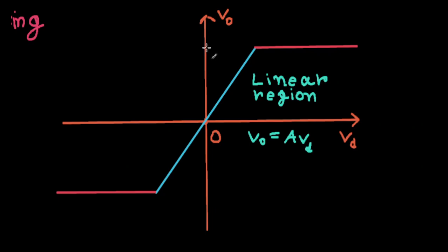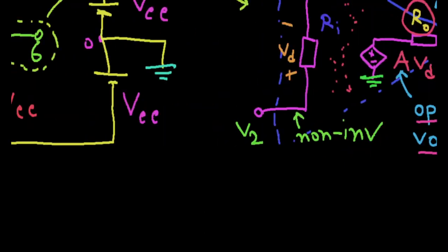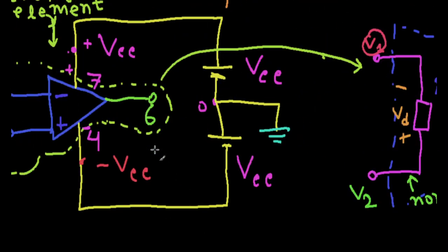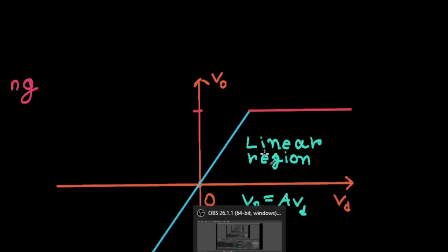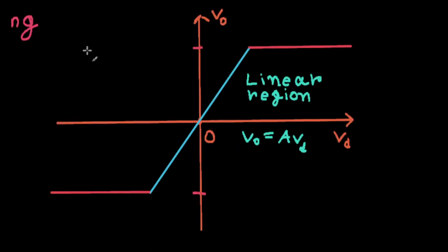Very interestingly, this is one other place, and might even be the last time or close to the last time, we're going to mention the power supply for the rest of the series. But anyways, the maximum and minimum output voltages here are actually limited or determined by your power supply. If you remember this, we'll just look back on it, the positive power supply and negative power supply. So this was plus VCC, this was minus VCC. In other words, if you just take the magnitude, it's VCC, and that is what actually limits the maximum positive and negative values here.